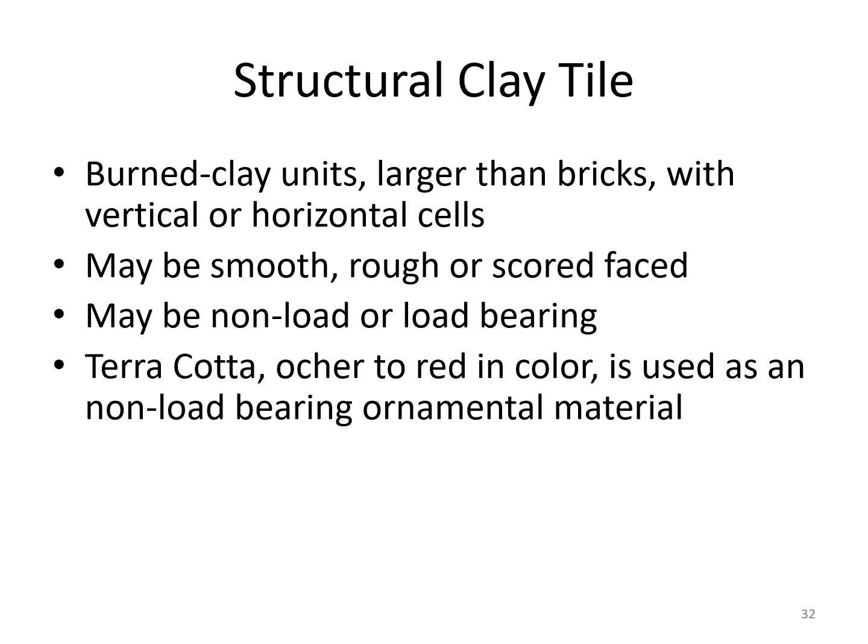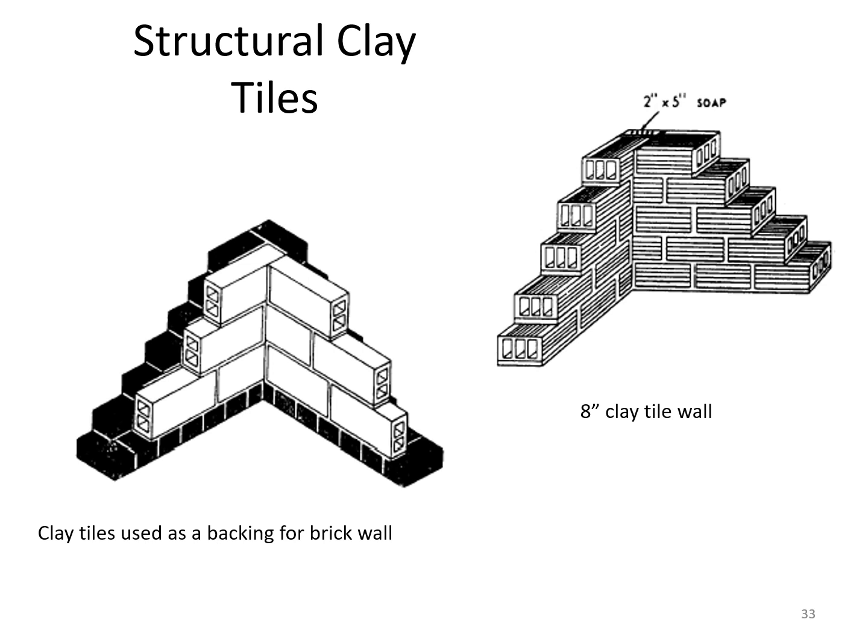That type is used in a non-load-bearing ornamental type material. You see those walls when they've been broken into very little lightweight pieces. Almost they make the sound of glass when they fall because they're fired at a high temperature. So here's a little bit more on the structural clay tiles. The clay tiles used in a backing for a brick wall, if you were looking at it that way, or the 8-inch clay tile wall.